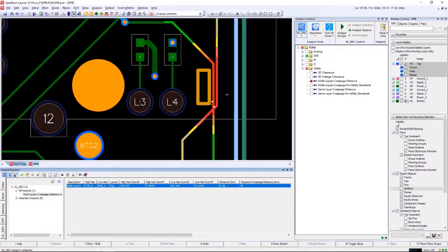You not only have to consider the floating object on the top side of the board, but then the victim nets in the distance through a hole in the board to the bottom side. So although the 1/3 rule is simple math, these checks can become increasingly complicated and time consuming when done manually.